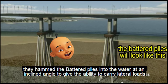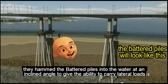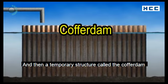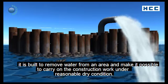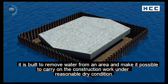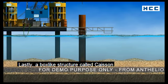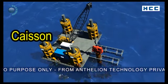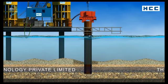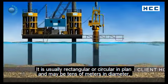Firstly, they hammer the battered piles into the water at an inclined angle to give the ability to carry lateral loads. And then a temporary structure called the cofferdam. It is in box or circular shape. It's built to remove water from an area and make it possible to carry on the construction work under reasonably dry condition. Lastly, a box-like structure called caisson is used as a foundation in construction work underwater. It is usually rectangular or circular in plan and may be tens of meters in diameter.